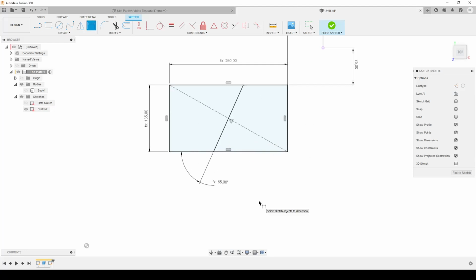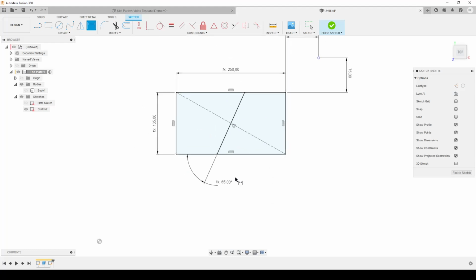As this is the manual way of doing it, you really don't need all the parameters. You can just sketch this and work from the sketch. But I like to use parameters to know what I do later. So let's see here now. We did that. That's the center line of a slot, and I want 2 more lines. Just going to make lines somewhere here, a bit off, so they don't get any constraints.